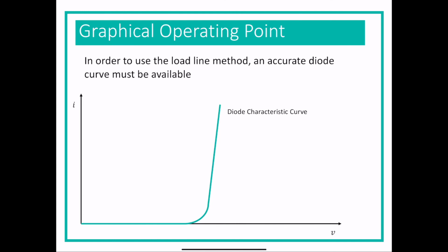in general, that can be obtained. There are devices called curve tracers where you can stick a diode in and you can print out a curve, and they work really well. We have several of them in our department. Or you can experimentally determine what the values are, but of course, if you were going to determine that, you would just go ahead and determine what the voltage was by measuring it. So in general, you do need a diode curve somehow, however you manage to obtain it. And you can actually mathematically determine it if you want. You can print out a graph of the values if you know the saturation value relatively well. That can be done as well.